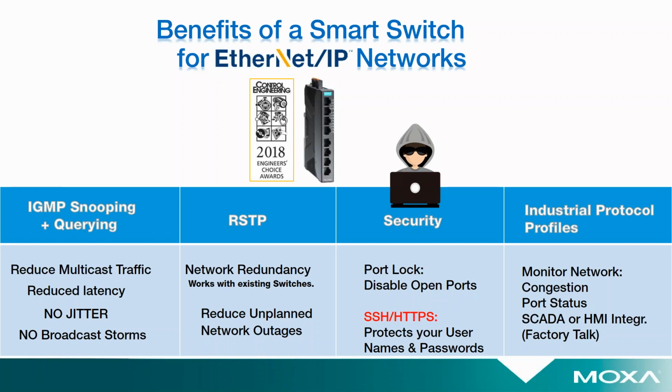Also, security, right? It comes with port lock, which basically disables any open ports. The reason that's important is because I'm sure a lot of you can attest to this, but I've talked to a lot of customers in my time, either in conferences or just in person whenever I'm helping them find solutions. And they can all tell you a horror story of a third-party field tech that came on down to the plant floor, forgot the manual or a driver for a configuration file, and just saw an open port on the cabinet and connected to it and brought the whole network down inadvertently.